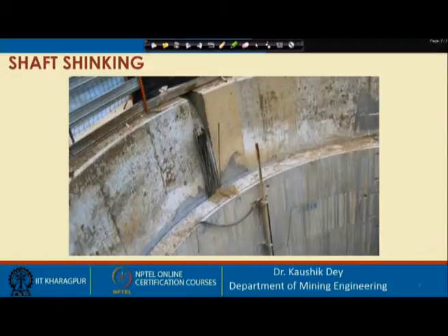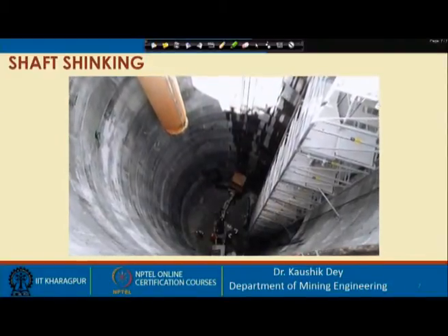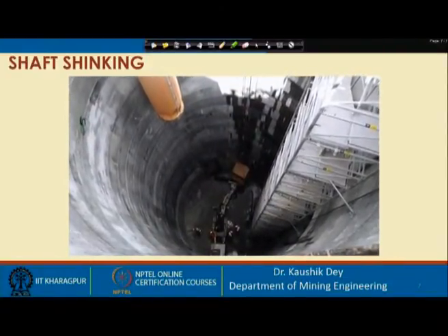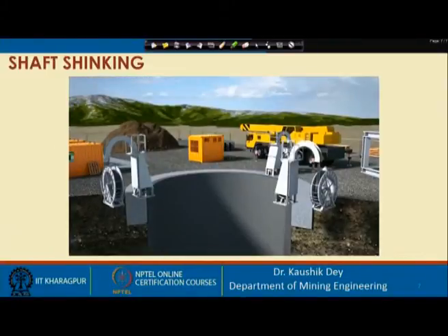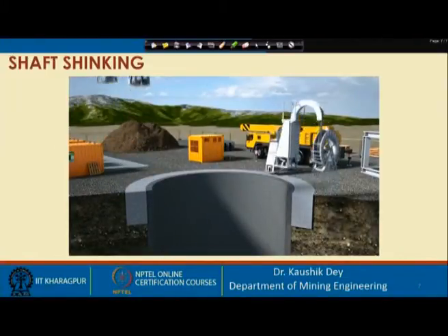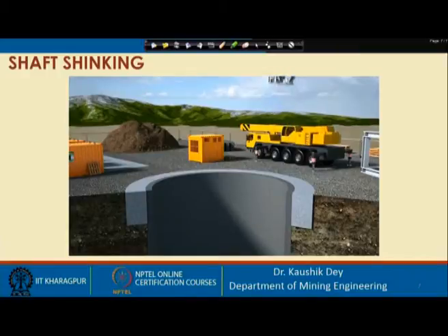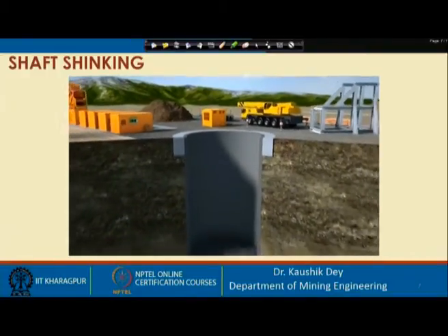Once the grout gains sufficient strength, the water in the shaft will be completely pumped out, and the shaft sinking may be completed. The shaft construction has been completed, and the grouting may be made without affecting the groundwater or the surrounding soil between the casing and the host rock. The shaft is now ready to be used.